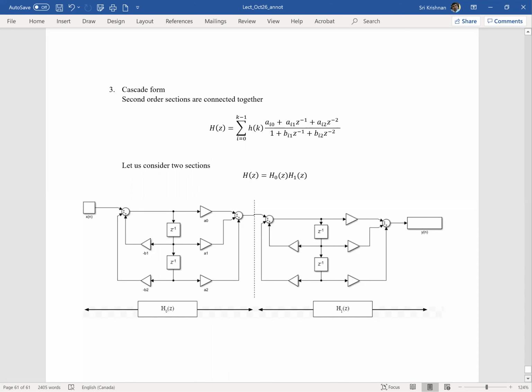So for example, this filter H(z) could be written as a product of 2 smaller filters, without losing any mathematical notation here. So the mathematical thing could be real, because this kind of representation, the Z domain, allows us to partition or have these factors with us. Each one could be represented as a filter diagram.